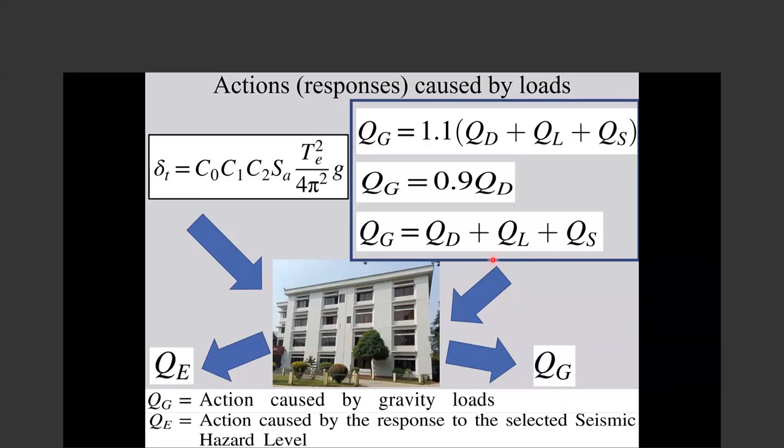But if it reached the target displacement, no force control element action... In an element we have different actions. No force control action reaches its lower bound strength. So then we can look at the deformation control actions and how much damage they do.